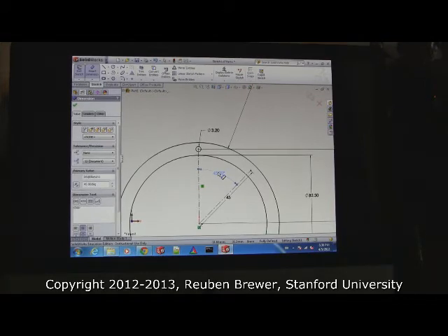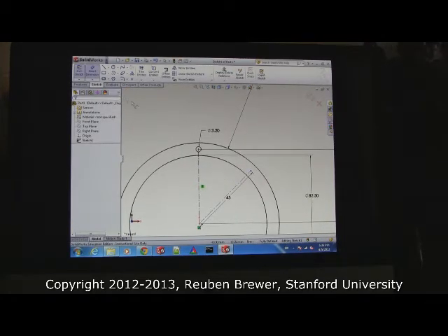Okay, now I want everyone to put a circle at the tip of that line. Okay, get smart dimension. Click the vertical line. Click the angled line. Now click in between them. Okay, guys. So this is an excellent point. Go ahead and delete that angle real quick. There's nothing wrong with it. We're just going to practice. This is another not zoomed in enough thing.